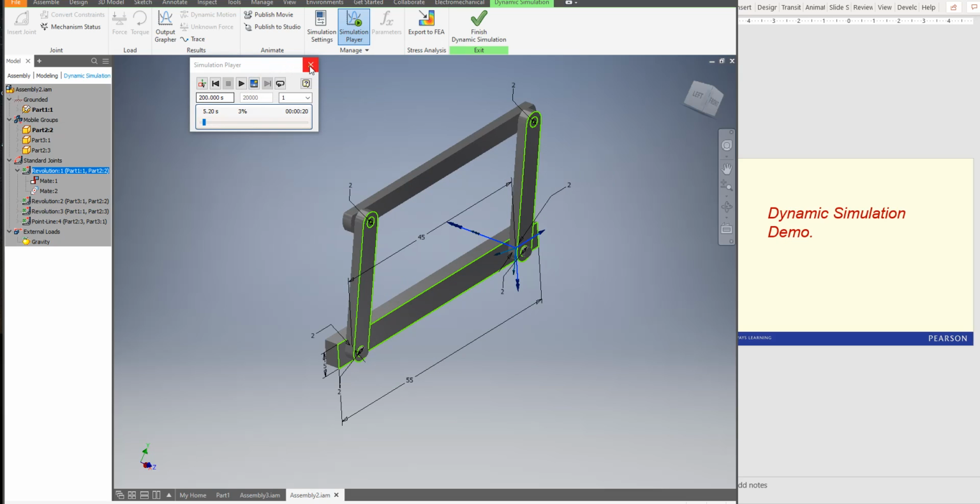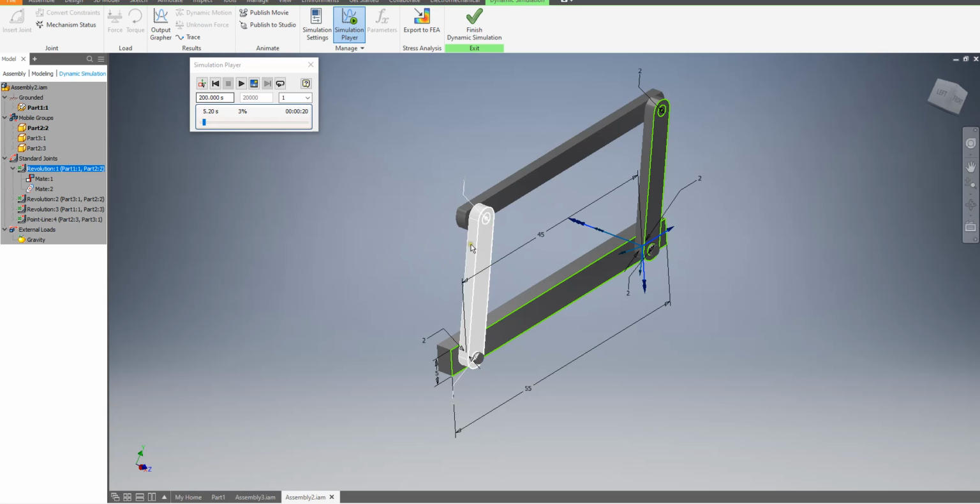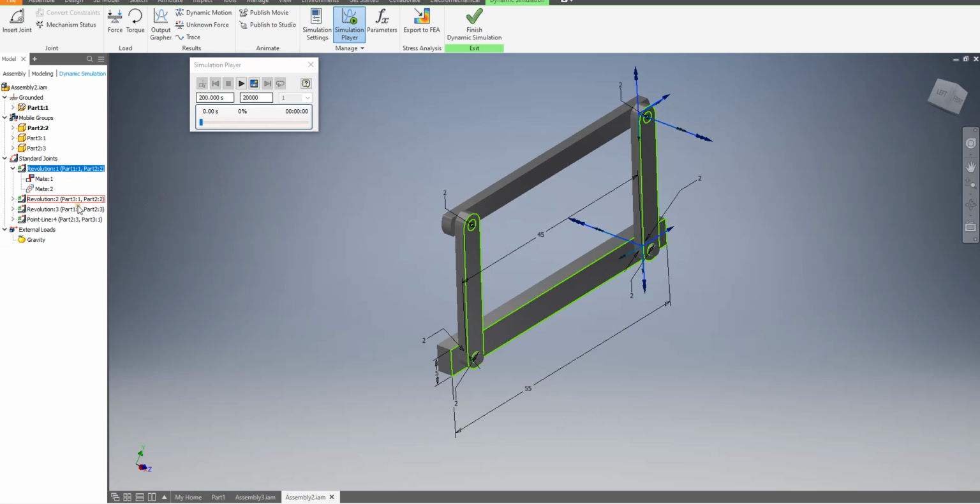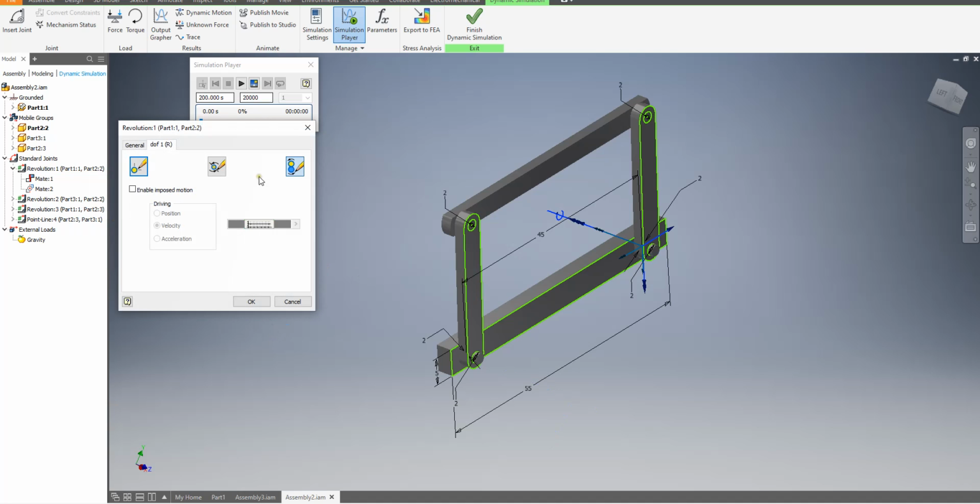Second thing, guys, say that I want to show in a graph, let me expand it, the force, the displacement and the velocity of the first joint only. Let me go back to edit mode. Okay. Just to remind you, I'm focusing on joint number one. I added on properties something here in the torque, which is friction, 0.5 coefficient.